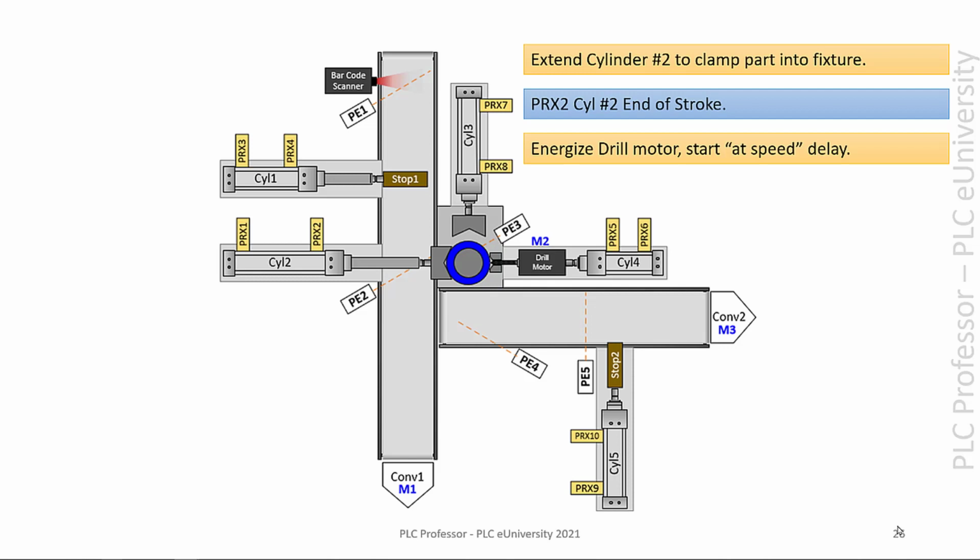Now you could have started up the motor earlier, because you knew you were going to push the part off. Remember that we don't want the drill bit to hit the part before it's up to speed. Because remember, what's at play here is the inertia of the armature. That's why the armature doesn't come up to full speed instantaneously, because it has inertia.